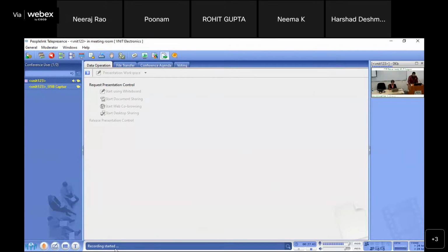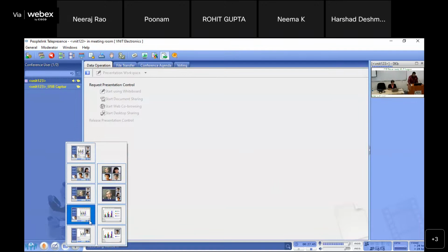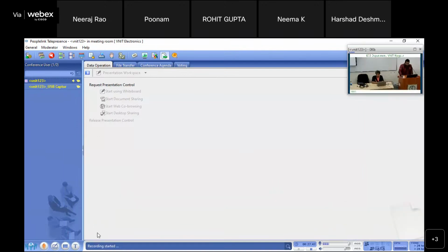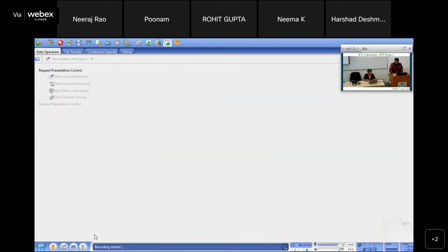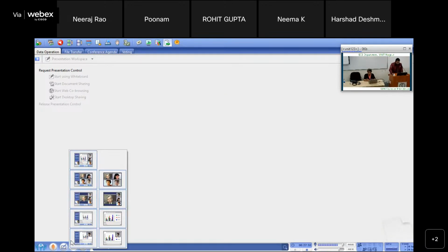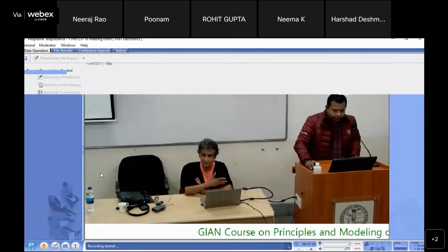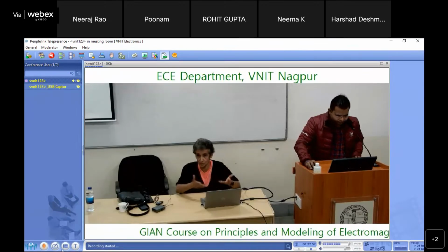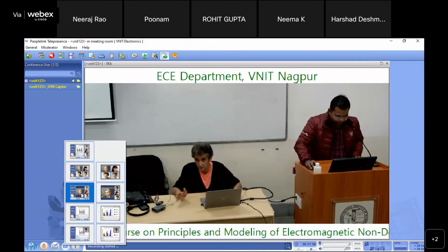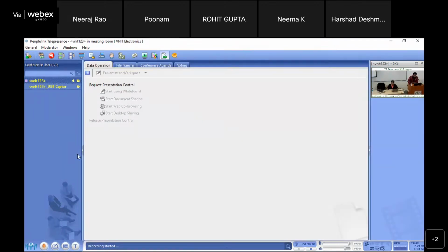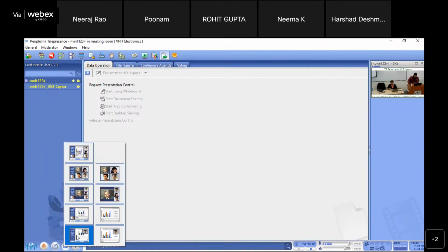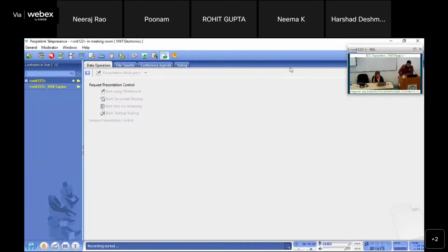Diffusion, you're always trying to calculate the unknown U, okay? But the governing equation varies in space and time in this manner. That comes out of Maxwell's equations. For eddy current, if I don't look at the steady state case, for a pulsed eddy current I really have a diffusion equation. That's what happens.